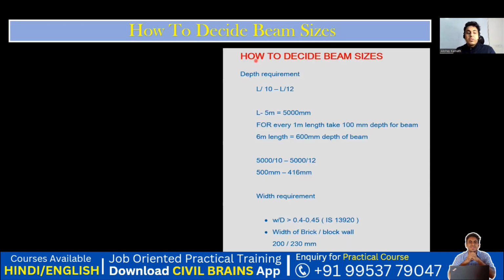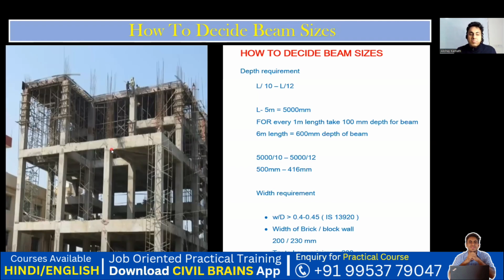So you might have seen these are the beams, and these are my columns. But what should be the breadth of my beam? What should be the depth of my beam? I don't know how to decide, right? For that we have certain thumb rules, and through that we usually try to do it. Usually the thumb rule is L by 10 to L by 12.